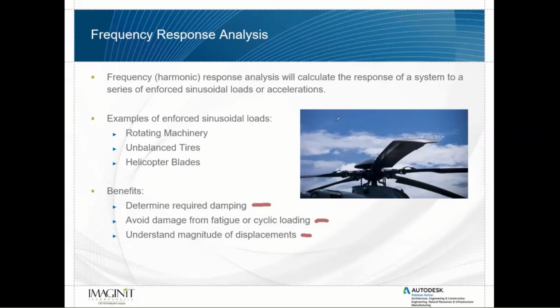So with frequency response, what we can do is we can take specific input frequencies. So we can go ahead and say, all right, we're going to test this from 10 hertz up through 500 hertz. Maybe we increment it every 5 hertz, and you can get what's called a frequency sweep. So you can check all the frequencies in a specific range and determine where your peak responses are. So basically, you'll get a plot that will look something like this, where you have some vibration occurring, and then you'll see a peak response in the displacement. It'll vibrate a little longer, and you'll see another peak response. So these peak responses are where the displacement and the acceleration increase due to that frequency being close to a natural frequency. You'll get these peak responses that you can then use to determine what the displacements and stresses are.